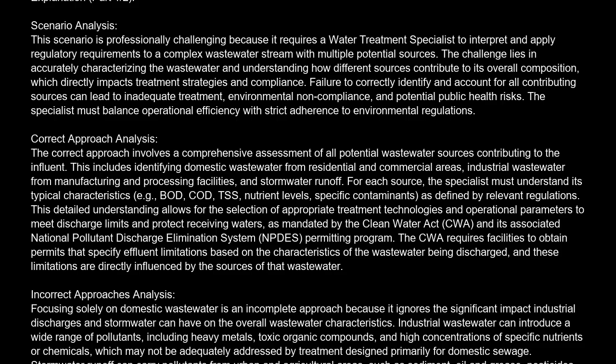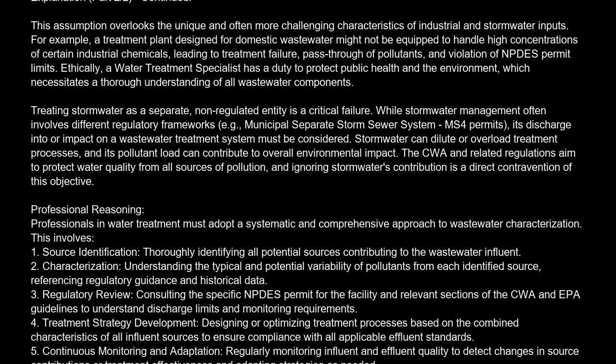Assuming all wastewater is similar to typical domestic sewage is also an incorrect and potentially dangerous approach. This assumption overlooks the unique and often more challenging characteristics of industrial and stormwater inputs. For example, a treatment plant designed for domestic wastewater might not be equipped to handle high concentrations of certain industrial chemicals, leading to treatment failure, pass-through of pollutants, and violation of NPDES permit limits.